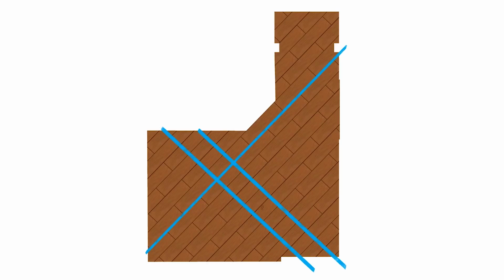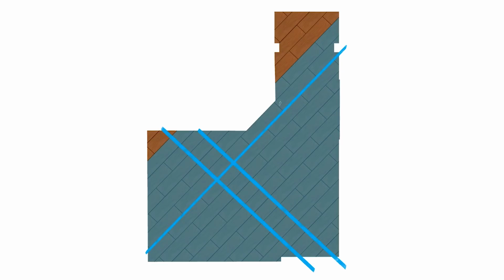Now, with those two lines established, we actually can't reach every part of the room. So if you imagine, we could measure out to here and we can catch these two tiles here, but we can't measure to this point or this point from this line over here. And then we do miss a little bit up here as well. So again, it's kind of minor, but to try to lay this out in the field, you can imagine, you're going to snap some chalk lines on the floor.